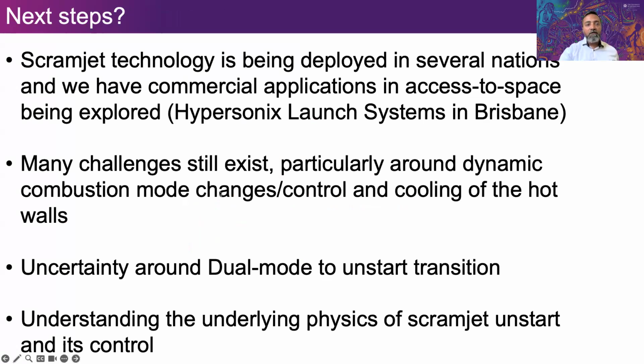So what are the next steps in my view? It's a technology that's being developed by several nations at the moment. There are commercial applications, including a startup company here, Hypersonics Launch Systems in Brisbane. Many challenges exist, particularly around dynamic combustion modes that I showed you today and leading to unstart, and how we control that. And another big challenge, if we have to have sustained scramjet flight, an ongoing challenge is the cooling of the hot walls and the materials we use to make this a viable technology.